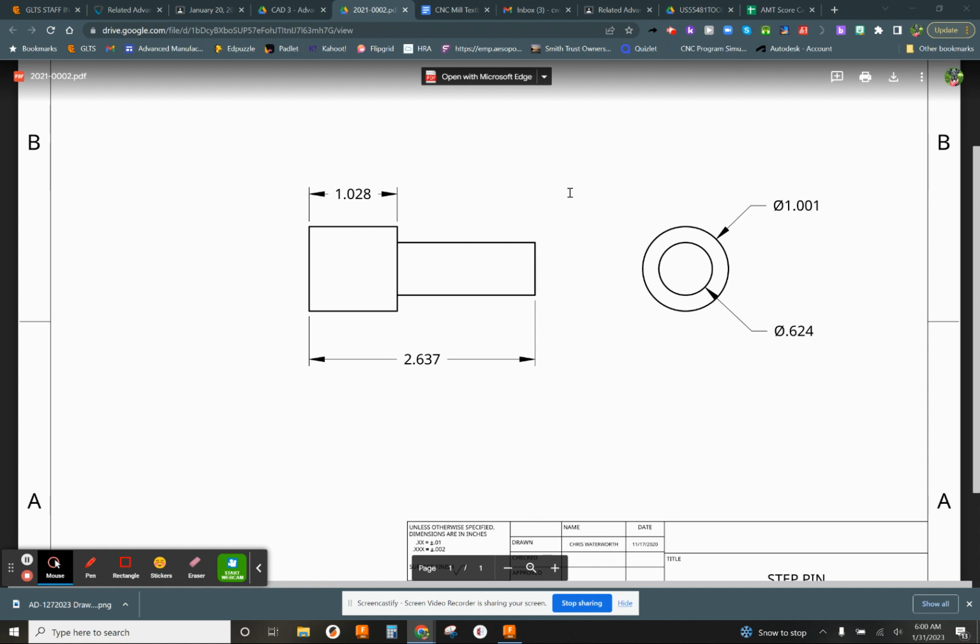So normally, if we're using extrudes, this would take two sketches and two extrudes to do it. But if we use the Revolve feature, we can just do it in two steps. So one thing you have to remember in a Revolve is that we're wrapping something around an axis. So all that's being done is we're going to have to create the geometry above this center line. All right. So this is all we're creating is this shape.